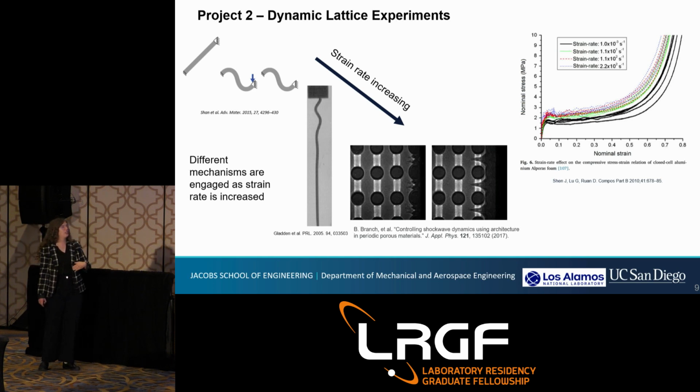And then as you start to increase the strain rate, in the center there, you get inertial effects where you have localized buckling behavior, and then eventually you reach the shock regime where things just change completely. But we do know that even at these lower strain rate regimes, the strain rate does actually affect the force displacement behavior of the sample.